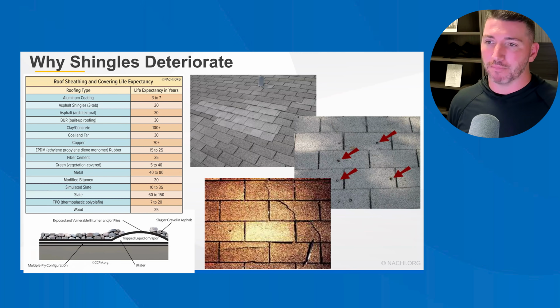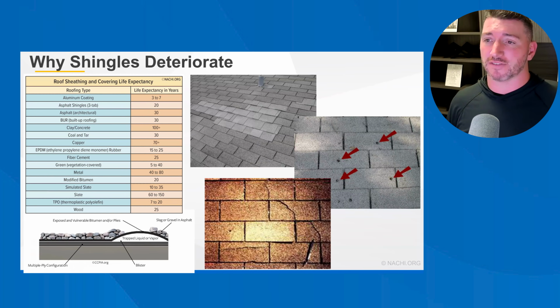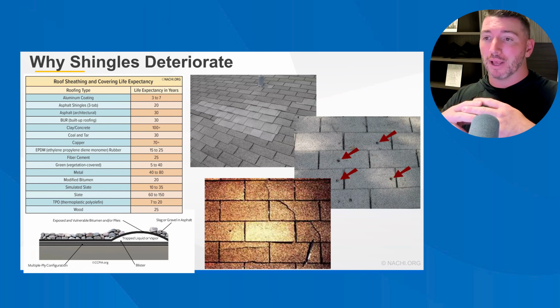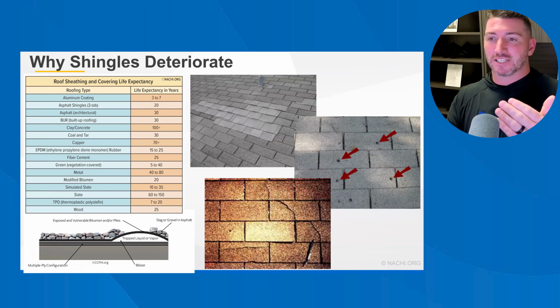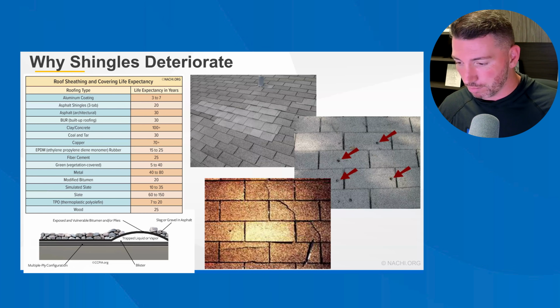I've heard it said a lot that poor ventilation is the reason those blisters happen. That's not the reason those blisters happen. It may be the reason why they manifest themselves sooner than they otherwise would have, but that trapped volatile gas is eventually going to make itself into a bubble and stress out the surface of the asphalt that it's trapped underneath and cause it to break at some point. Again, it'll deform the asphalt and cause an unpopped blister, even if there's not pressure inside that blister. The initial pressure will cause a permanent plastic deformation in that asphalt, and that asphalt will stay that way even if it never pops. And so that's just the reality of the situation with blistering.